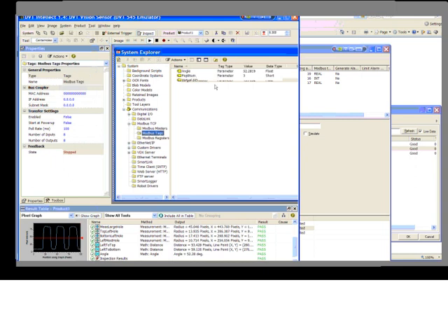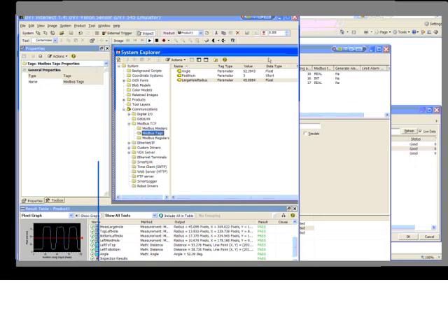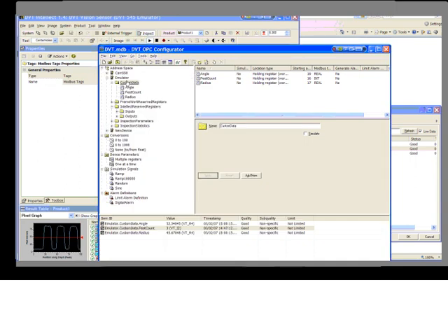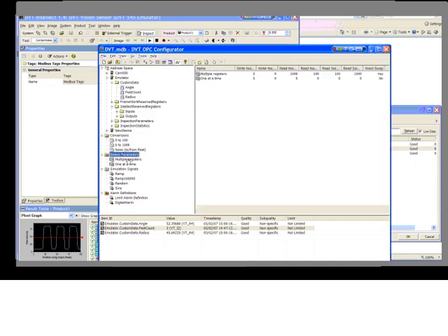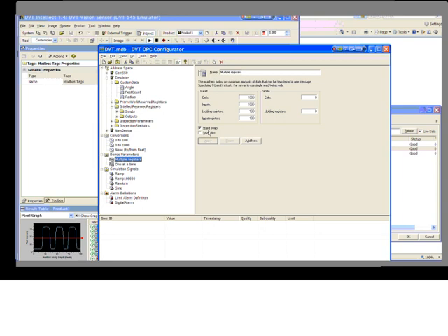So I've created Modbus tags here. You also have to make sure that if you're transferring anything other than a 2-byte value, you specify any device parameter that swaps words so that the OPC clients can interpret those numbers correctly. Otherwise, you'll get numbers that don't make a lot of sense.